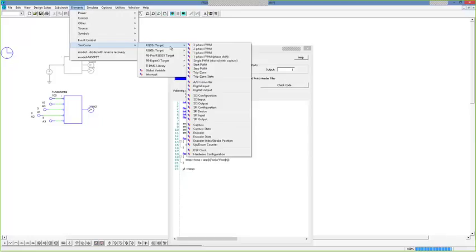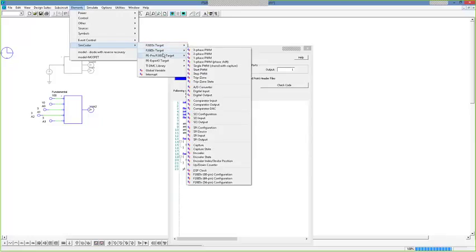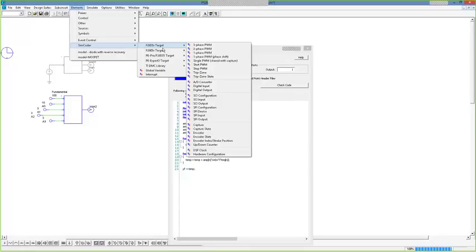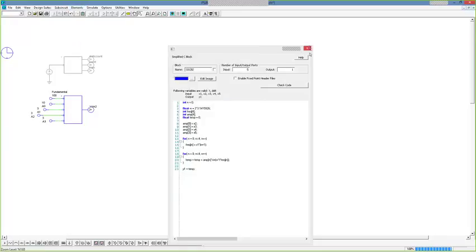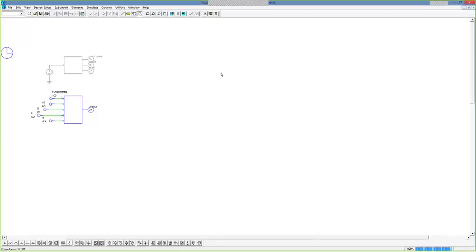So the F28335 or 33X and the F2803X from Texas Instruments. Only those DSPs, and that handles the peripheral definitions. If you just do generic code generation, you will be able to translate a digital control schematic into a general schematic. So let's have a quick look.